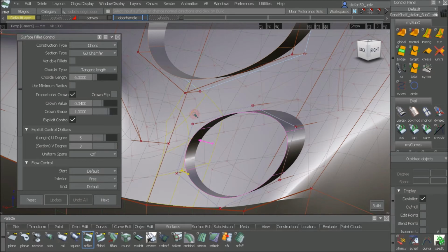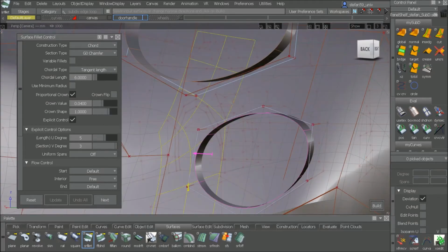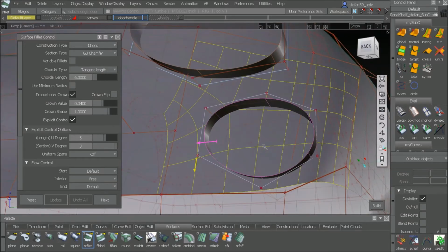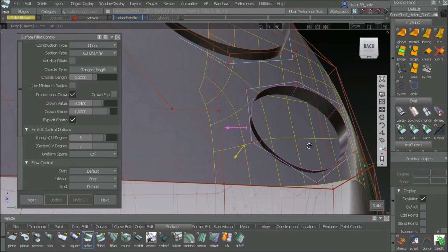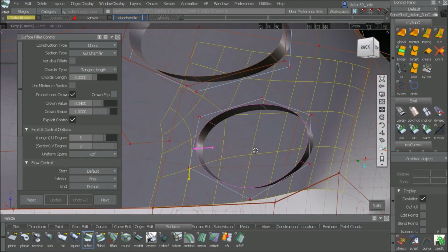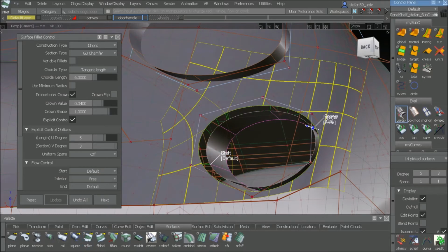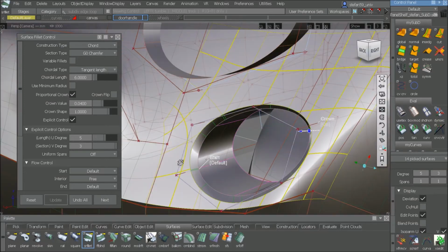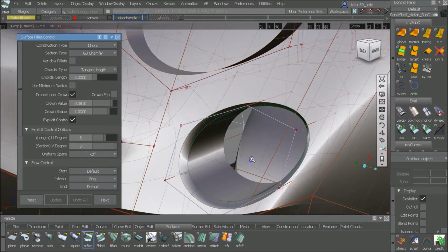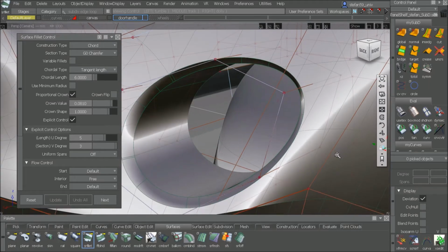Additional faces, of course, are involved. So I have to keep them all, take them all, sorry. And then check the arrows: inside the yellow one, outside are the magenta. That looks good. And let's say, okay, build it. Let's see what we get. Not so bad. And after that, we need the glass for the lamp inside of this.